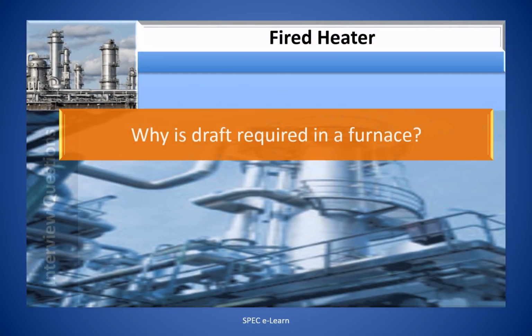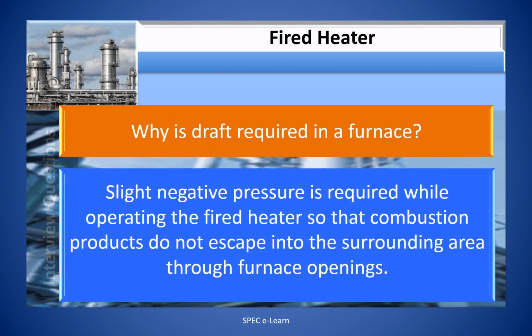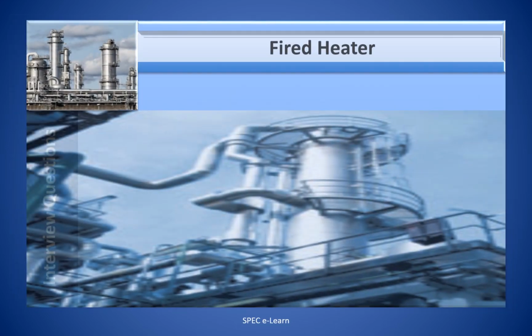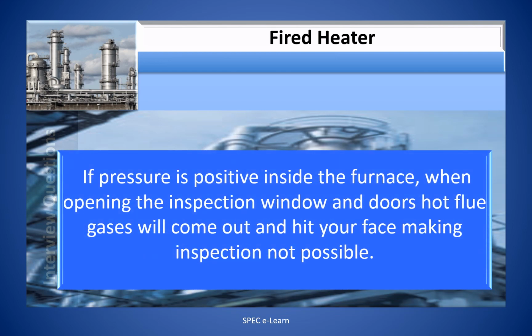Why is draft required in a furnace? Slight negative pressure is required while operating the fired heater so that combustion products do not escape into the surrounding area through the furnace openings. If pressure is positive inside the furnace, when opening the inspection window and the doors, hot flue gases will come out and hit your face, making inspection not possible.